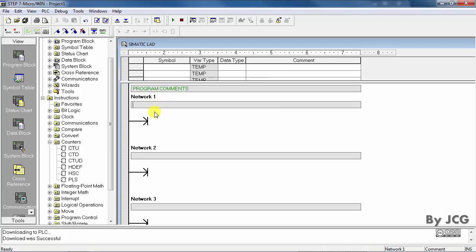I'm gonna remind you of the equation. So the equation is reset inverted and the set or the memory itself. And this is the equation of the memory. So I'm going to build this function. It has an OR function, an AND function, and also a NOT function. For this, my set is going to be the black button, and the reset is going to be my red button. So in order to build this function, I just need to do these operations.